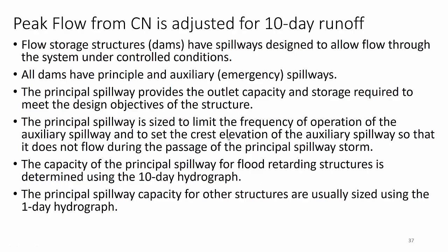Peak flow from curve number is adjusted for a 10-day runoff because flow storage structures, dams, have spillways designed to allow flow through the system under these controlled conditions. And that means you need to have a 10-day, a long term of runoff, because it doesn't just happen within the day of the storm.